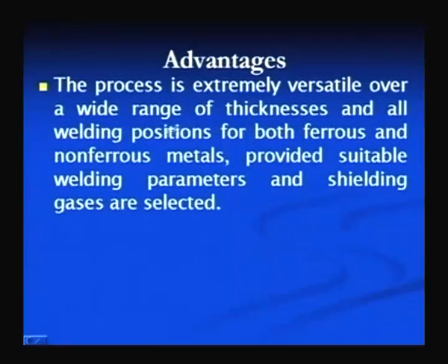Now, we will see some of the plus points related to gas metal arc welding, because of which it is extensively used in industry. This process is very versatile and it can be used for a wide range of thicknesses and for welding in all positions of both ferrous and non-ferrous materials, provided we select the suitable combination of the parameters and the shielding gases.